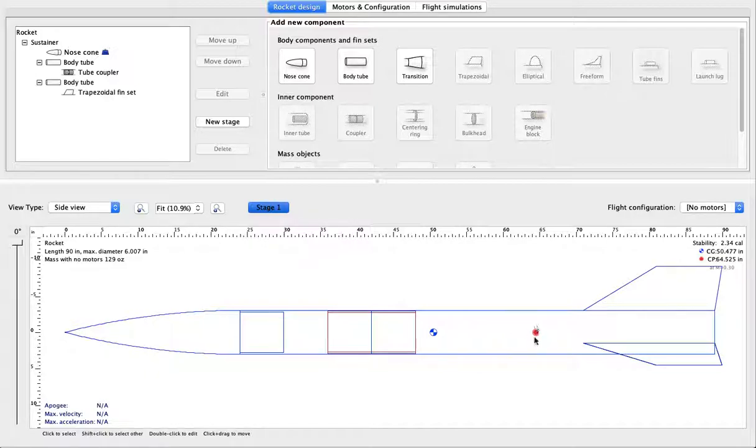You always want your center of pressure behind your center of gravity. If I could demonstrate this in some kind of experiment, I would, but I just have a screen. I don't really have an analogy, but you always want this right behind the center of gravity. Now, this is going to change as we add propellant, as we fly, and then that's when you have to plan ahead with your avionics bay, what weights you have in the front, and all sorts of things. So we'll cover that.